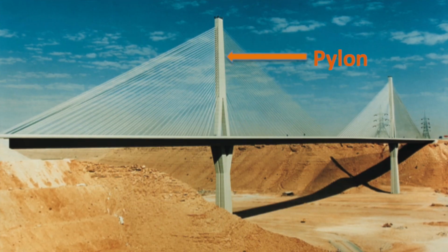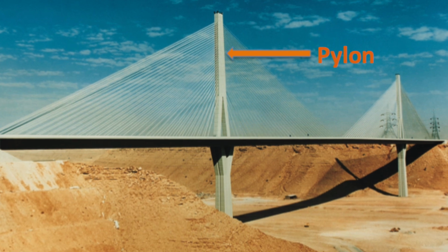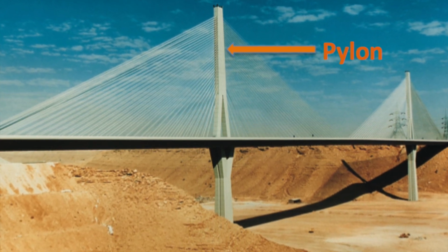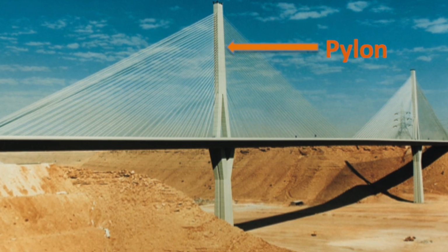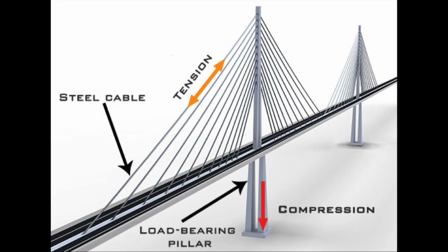The pylons are a crucial part of any bridge. Compared to other bridges, cable-stayed bridge pylons hold the entirety of the bridge weight. Essentially, the two parts of the bridge that the pylon supports on either side balance each other out to make the moment around the pylon equal to zero. The weight of the bridge translates to the compressive forces in the pylon. Additionally, as the height of the pylon increases, the compressive force decreases because it is spaced out throughout the pylon. The pylon is then supported by the foundation.